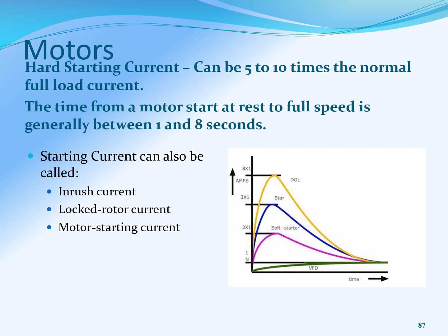Some of the things you might want to keep in mind with this slide: I might ask you guys how many times the normal full load current is the inrush load on a motor. I know I saw that on my distribution exams, so I'm going to ask you on your exams as well.